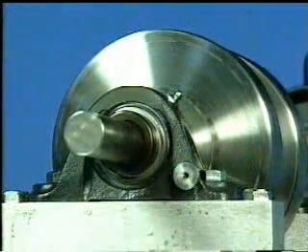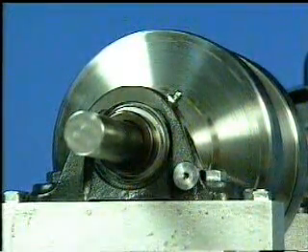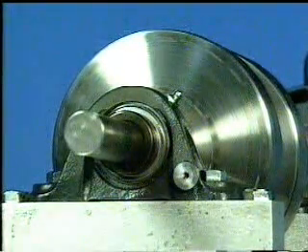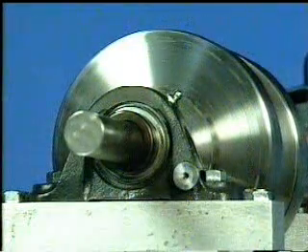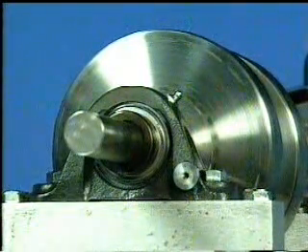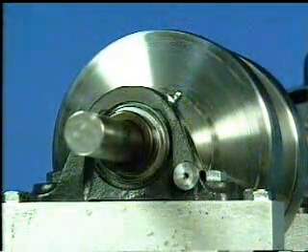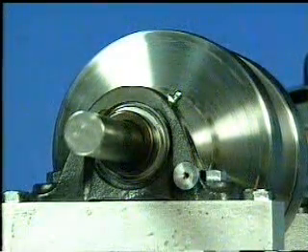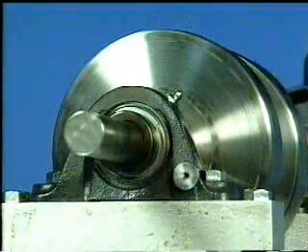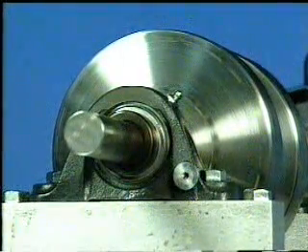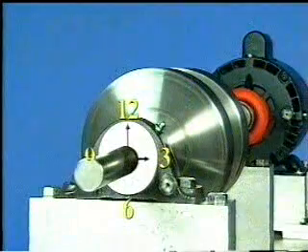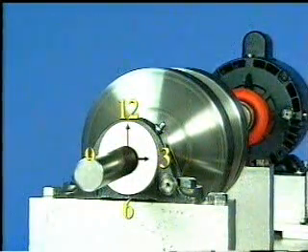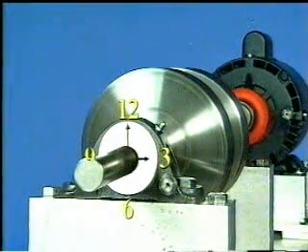A bearing cocked on a shaft has the same phase characteristics as a shaft that is bowed between the bearings. As the shaft rotates, it tends to force the cocked bearing to correct its position. Because it cannot be forced into a correct position, the bearing can actually force a bend in the shaft and exhibit characteristics similar to a bent shaft. The axial direction will produce phase data 180 degrees out from side to side or top to bottom of the bearing.